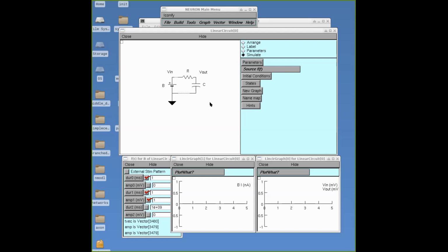It'll be exponential decay, but just with the opposite concavity. Yep, exactly. So on the way up, it's going to be concave down, and on the way down, it'll be concave up. And it'll be continuous. V out is not going to jump abruptly. V in will jump abruptly, but we know that that's just a fiction, because electrical potential nowhere changes instantaneously. And we can talk about why that is sometime if you like.